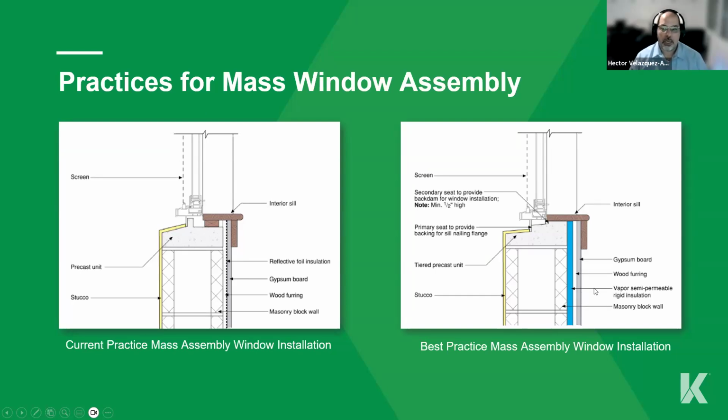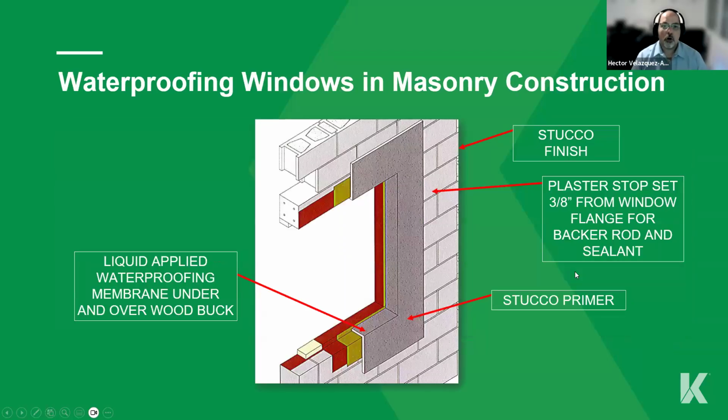The best practice that we highly recommend is having a system or an entire precast unit sill that looks like this, like where Nick was saying, gravity is our friend. So let's try to get the water always away from my structure, especially from the inside. So we have a slope here of the window that is going to come to the front of the window, and then it continues outside the window. So that's what we're trying to always achieve, and it will help as well to avoid getting water into my unit.